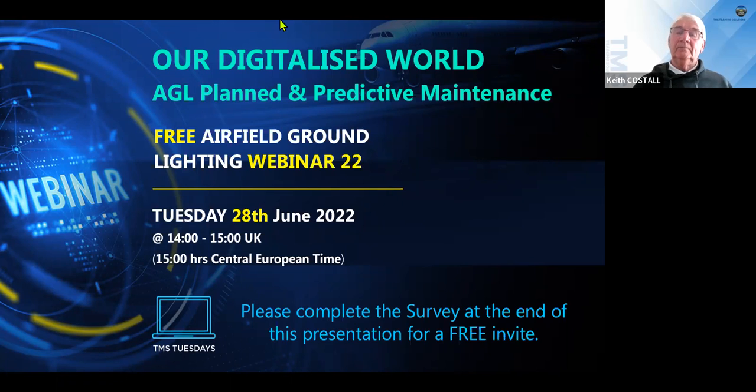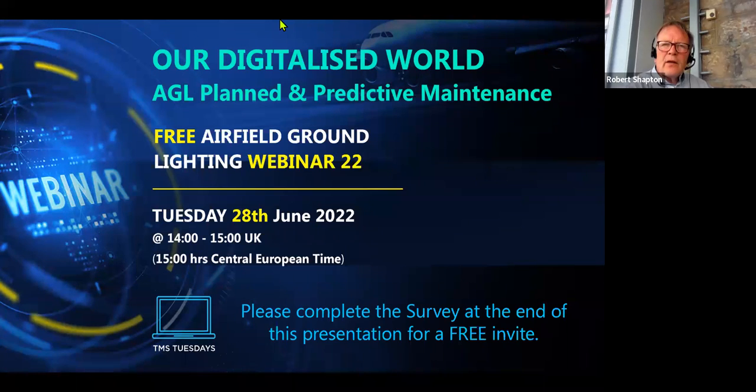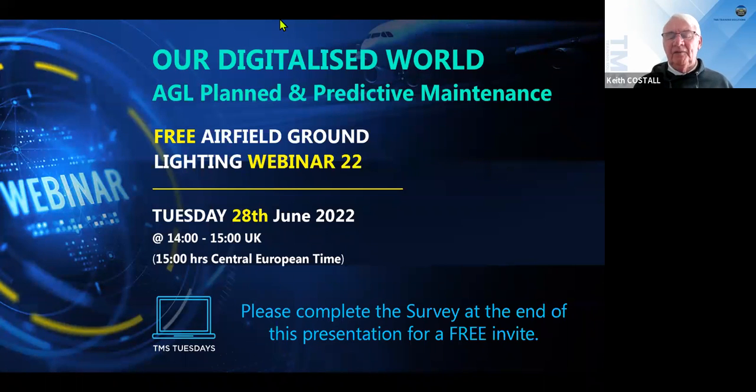I've just a question here, an anonymous question. Is there any standard that needs to be followed regarding the alphabet, number and direction sequence? It means starting from left to right direction, placement of numbers, letters, and direction of sign, etc. Well, yeah, in the design of a sign itself, the legends, how far they are from the physical edge of the sign, the fascia, etc. All that is in either Annex 14 or in the Aerodrome Design Manual Part 4. So I think that should be sufficient to answer that question.